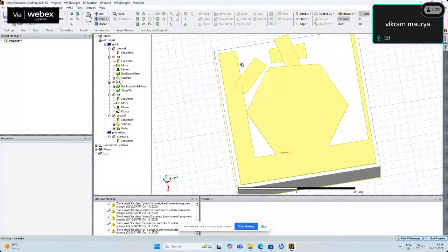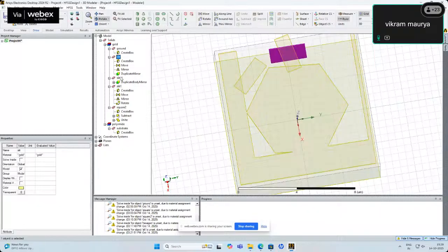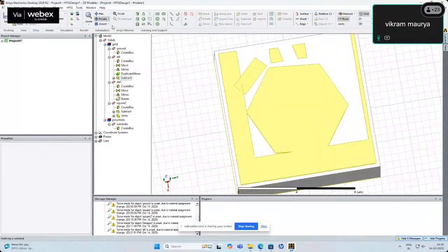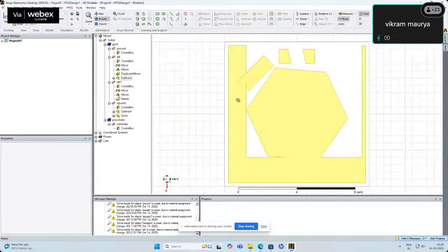All we can do is to click that box. If this particular structure is needed anywhere later in optimization or designing, I simply will click on that clone tick box. But if we don't need it, we can again delete the subtraction operation. We can also delete this clone operation. And we will simply select these two and subtract without cloning, because we actually do not need that. If we do not need that, we don't have to clone it again.